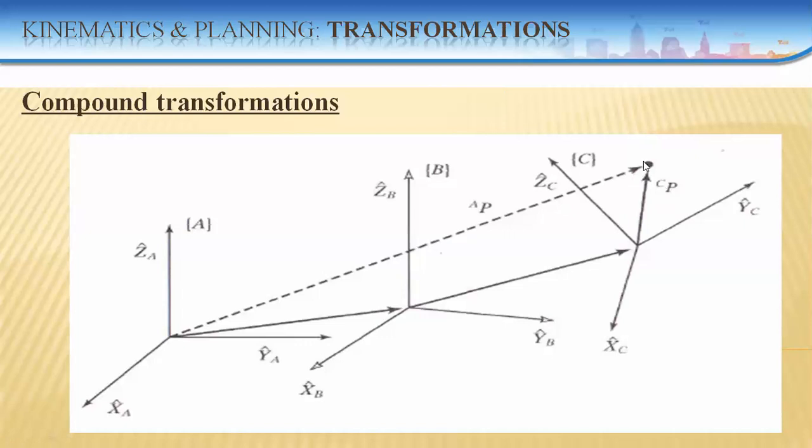Here from 60 degrees to 30 degrees, that is minus theta needs to happen, and a negative translation needs to be taken if it has happened during forward kinematics towards x, y, z, and simultaneously in the three coordinate systems it needs to be retracted.